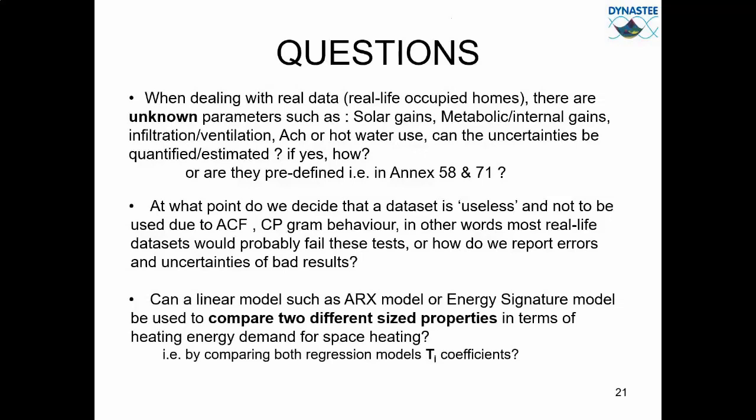Anyway, in all these methods, there is a way of introducing the uncertainty you have in each of the measured signals, and each of the methods, LORD, CTSM, or averaging or regression method, will be able to propagate this uncertainty to the estimated values. So if you have a big uncertainty in one of the signals that is very important for estimating a parameter such as the heat loss coefficient, then the uncertainty of the estimated heat loss coefficient will be very high.